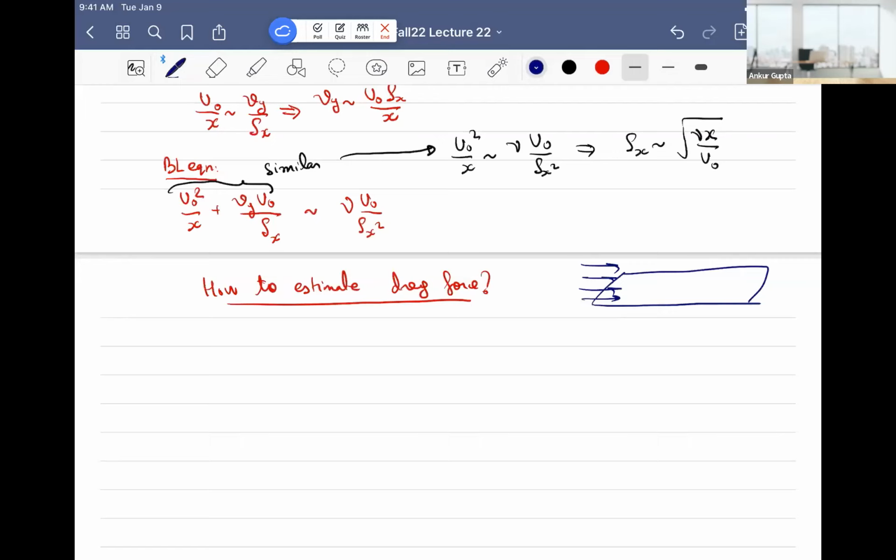In a cylinder, you can imagine we can also be using pressure force to apply a drag, but here we're just applying a surface drag, and that's called skin drag. Because it's parallel, it's only because of the shear, and we'll discuss skin drag in a minute. But for now, what's interesting to us is to estimate the tau.